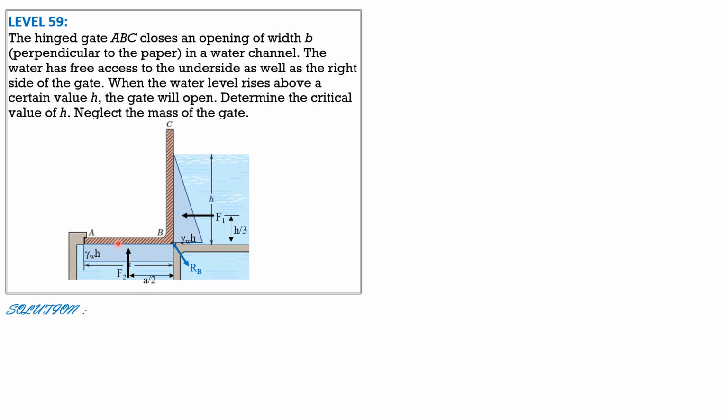So since weights of gates are negligible, that means there's no reaction here when the gate is about to open. So the opening is in such a way that this gate is about to rotate counterclockwise, so there will be no reaction here. So that means summation of moment about B equals 0.